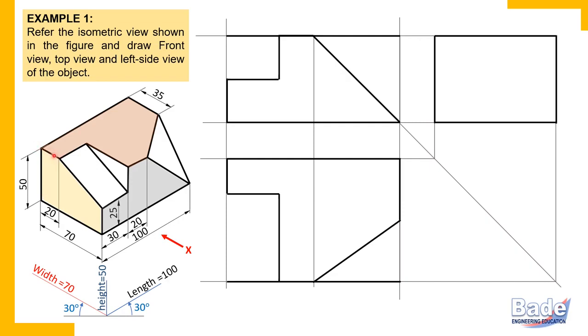Now this is one more principal edge which is 20 millimeter. So measure 20 millimeters. Better measure 20 millimeters independently. But otherwise, this edge 20 millimeter long is common for this surface and this surface. So this edge we have already drawn here, 20 millimeter long. So you can project this edge here in the side view by drawing projectors in this manner.